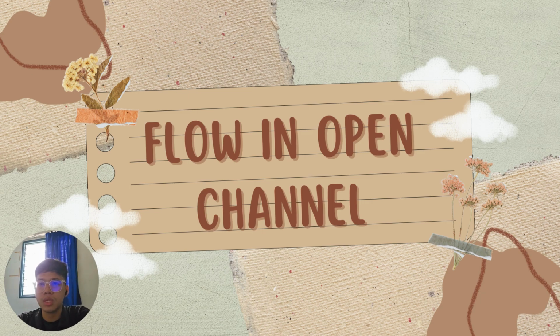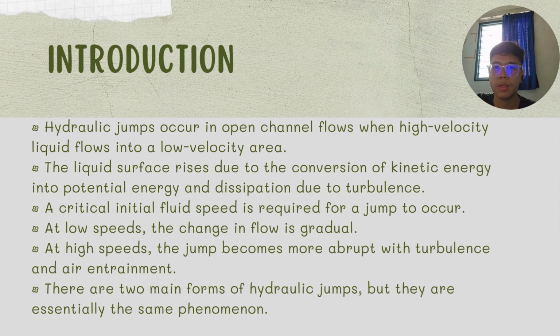Today I want to present about flow in open channel. This is an introduction. Hydraulic jump occurs in open channel flow when high velocity liquid flows into a low velocity area. The liquid surface rises due to the conversion of kinetic energy into potential energy and dissipation due to turbulence. There are two main forms of hydraulic jump, the first one at a low speed and the other at a high speed.